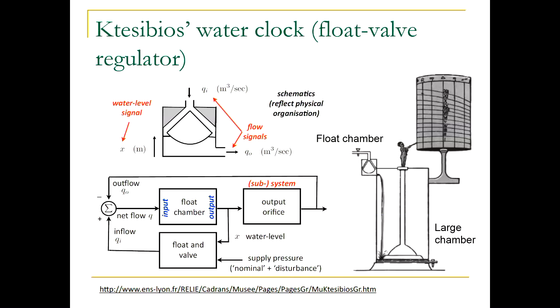This chamber is actually enlarged here. So this is a zoomed-in version of the chamber. So water flows in from the top, but then there is this float inside. So for instance, if there is more pressure on top, so there's more water in the lake where the water comes from, then there will be more inflow here. But then the chamber would fill in here, and this float would push the vent. It closes it down. So if it's designed well, you can make it so that the level of water here is maintained pretty much constant despite the disturbances, how much water there is in the lake.